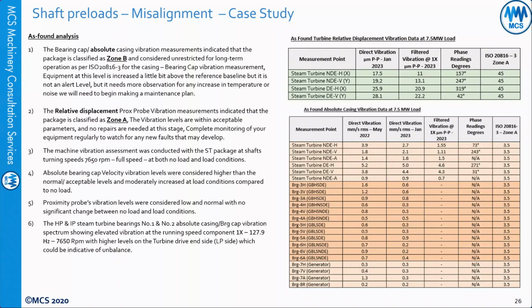Thank you so much for that. Same case study here. Why are the probes attached at a difference of 90 degrees? Why not 180 degrees? Because, as I mentioned, this was an older machine, and these were the only holes available for this bearing design.